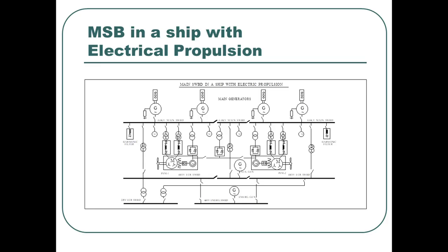How are these advantageous? Why does the current come into the picture, and how is current reduced when you use higher voltage, with the power factor, for the same power of the motor? When you increase the voltage, your current is going to reduce drastically. So that is the reason why we are more concerned about high voltage. Then we saw advantages and disadvantages of high voltage system.